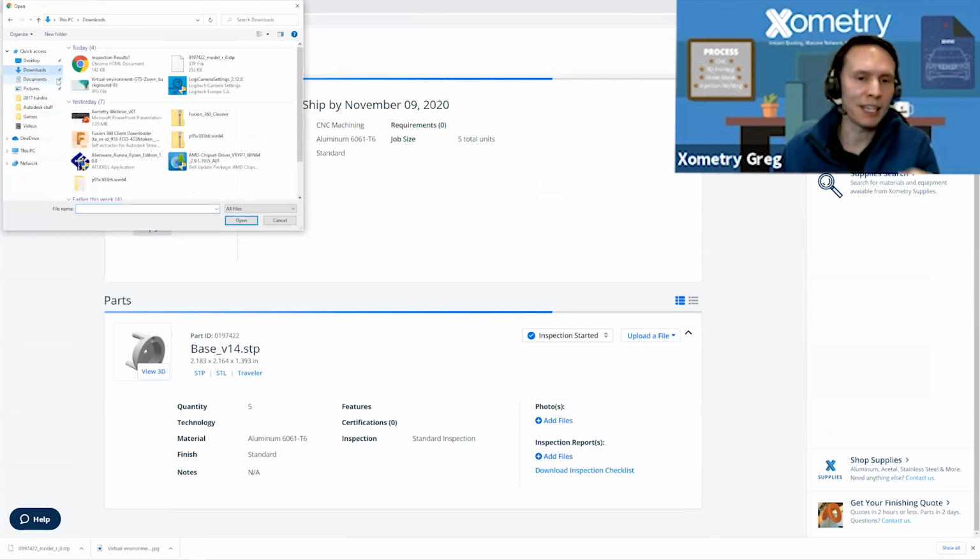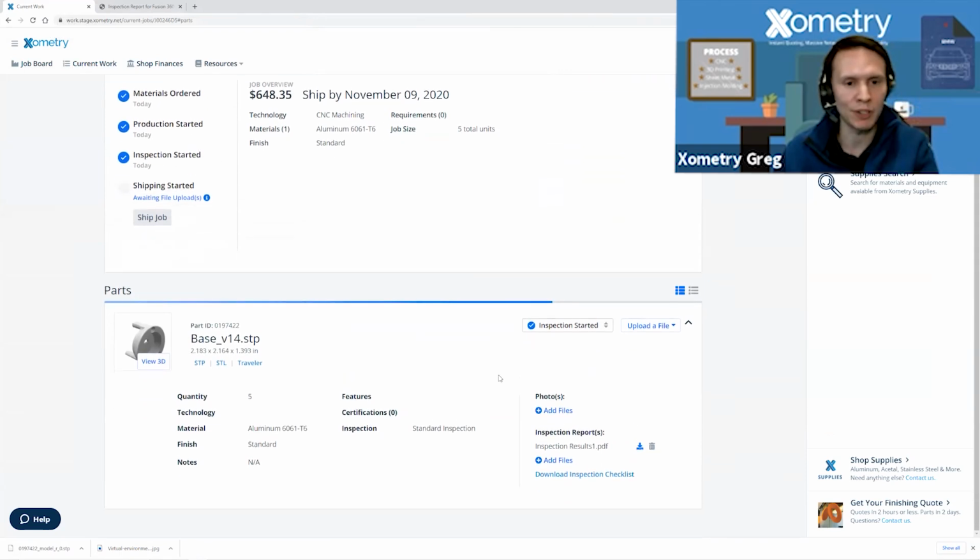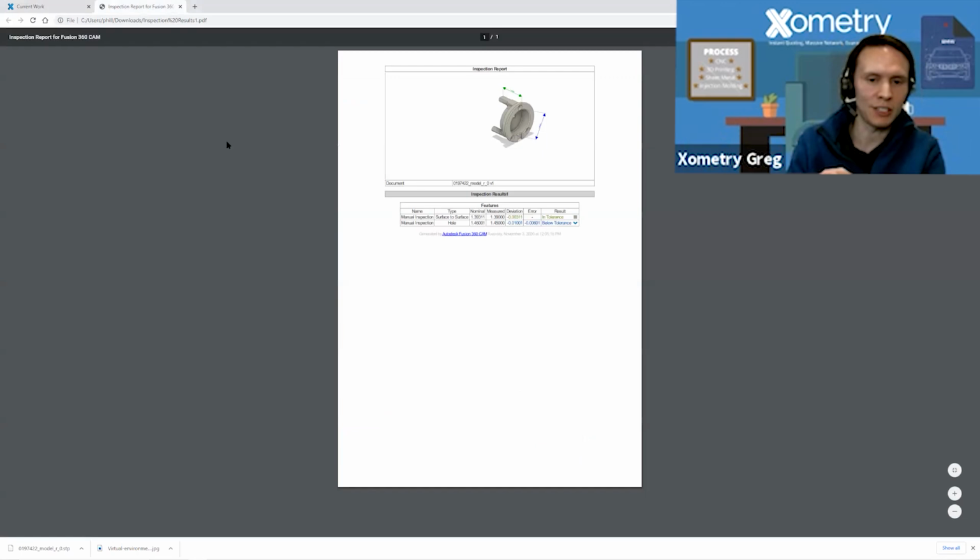We also have our partner guide that has all the criteria that you possibly need to understand what the inspection requirements are. So, if a customer asks for a formal inspection report, that's a deliverable. That's something that's folded up, placed with the part, and delivered to the customer. Definitely the same for like a CMM or AS9102 style report. Those are all ones that are deliverables. Same thing with material certs, COCs. We need the digital file attached with the part itself, but those things are also going to the customer, so they need to be in your box, and you'll see that on the shipping checklist.